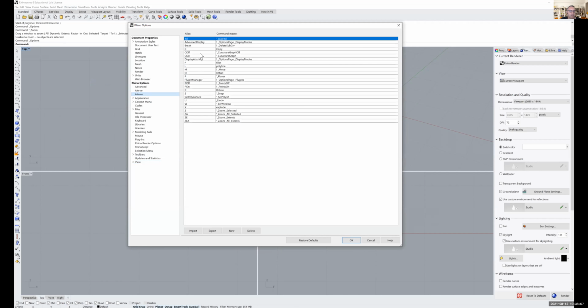So really, if you find yourself using a command more than a couple times, so copy, line, move, offset, rotate, and some of them you may never use. Like I didn't realize that U was undo because it's Control Z. But if you find yourself using the same command over and over, I would make an alias with it. And so that's a huge time-saving thing because if you're right-handed, you'll use your mouse with your right hand and you can have your left hand on the keyboard, in the same way that you might use AutoCAD or something like that if you're used to that.